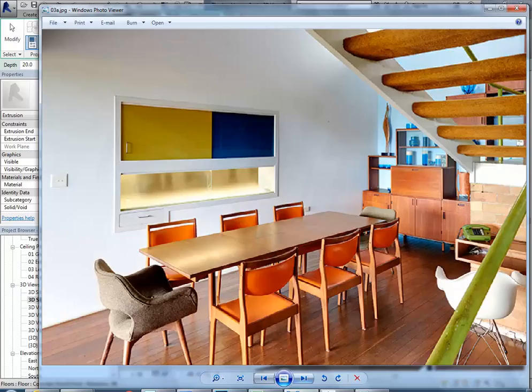Well, I'll ask you, do you know what that's called? The thing going around. Yeah, it's kind of a frame. Yeah. Skirting, yes, skirting it would be if it was covering up that gap there. But otherwise it's an architrave. So that's an architrave going around that edge there, which actually performs the same function as a skirting or a cornice, and it's covering up the junction essentially. And so the depth there, it's a fairly narrow one, so it might be 50.